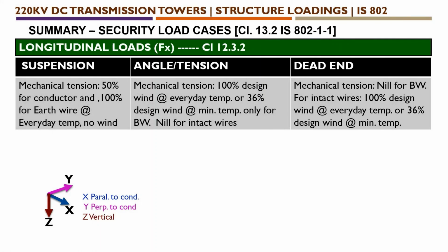Similar to the reliability load cases, we are going to calculate 3 directional loads here: longitudinal loads, transverse loads and vertical loads, FFX, FFY and FFZ respectively. This is as per clause 12.3.2 of IS 802 part 1 section 1. So here are the cases.